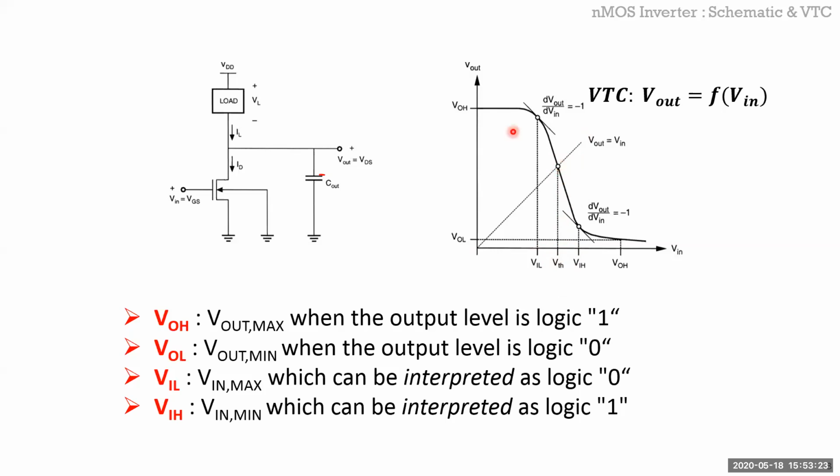Okay. So when this transition is happening, there is only one point where Vin is equal to Vout. And obviously that point is always there, because if I draw this line, which is Vin equals Vout, it'll always intercept this curve. So there is always this point, doesn't matter which inverter, how you do it, unless you completely mess up the inverter. So that is called the threshold point. And when you're designing gates, that's usually what you design for, adjusting your noise margin and stuff like that.